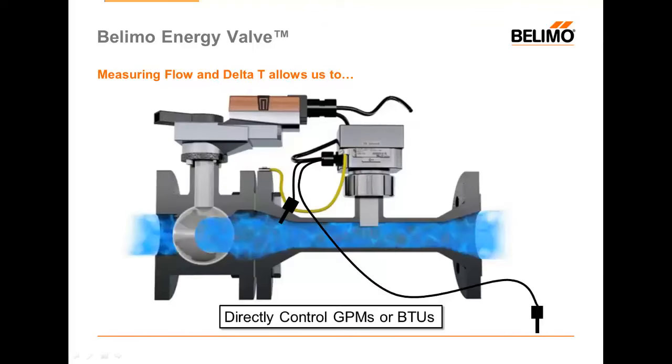If we're measuring flow and delta T, we can also control directly to GPM or to BTU. We're measuring both GPM and BTU, and therefore we could correlate our control signal to control either one of these two items.